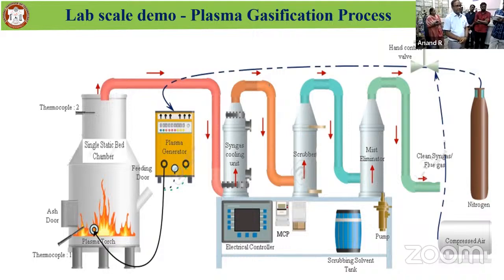In the gasification mode, the products will come out in the form of solid, liquid, and gaseous things. In general, it is only 2 products: one is solid, and the other is gas. The condensable gas we can say is a liquid. The non-condensable gas is a synthetic gas, along with carbon dioxide and traces of other gases, which can be used either to produce heat or in an engine for producing power. The heat from the non-condensable as well as the condensable gas can be recovered. If we install this in any hospital, we can use the non-condensable gas as a fuel for producing heat for different applications.